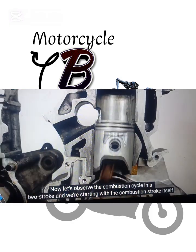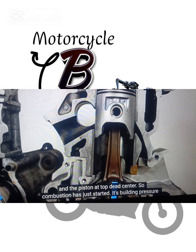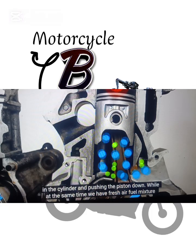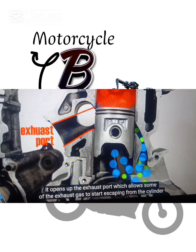Now let's observe the combustion cycle in a two-stroke, and we're starting with the combustion stroke itself and the piston at top dead center. So combustion has just started, it's building pressure in the cylinder and pushing the piston down, while at the same time we have fresh air-fuel mixture below the piston, and I'll explain how it got there in just a moment.